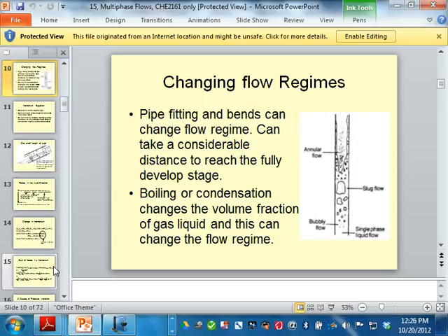The density is not going to be the same, is it? The density will be reducing, or the specific volume will be increasing. So when the specific volume increases, m dot is the same, area is the same, what happens to the velocity? Increase or decrease?